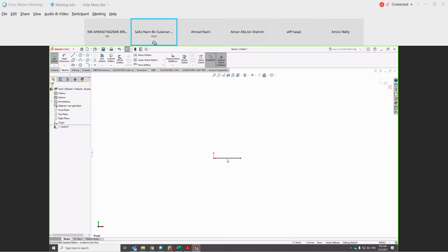Okay, so kalau you nak move, you want to move your part, you can also use zoom in, zoom out at the different point of your cursor lah. So itu untuk zoom in, zoom out. And then satu lagi, kalau you nak move pun, you can use control button, hold, and then middle mouse button, drag up and down, left and right.